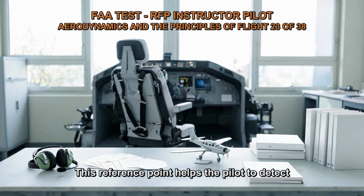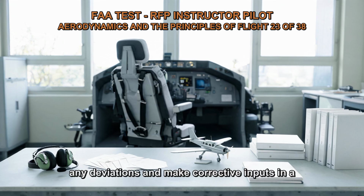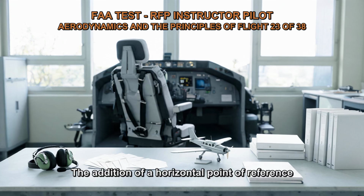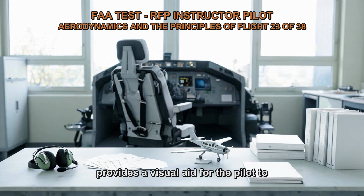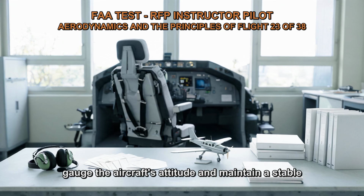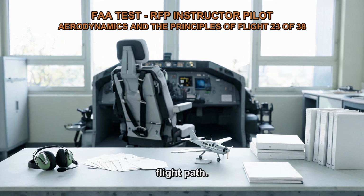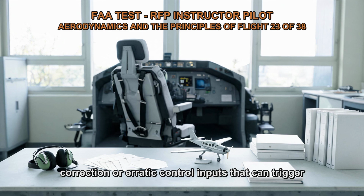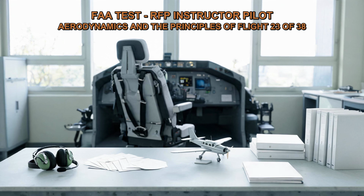This reference point helps the pilot to detect any deviations and make corrective inputs in a more precise and controlled manner. The addition of a horizontal point of reference provides a visual aid for the pilot to gauge the aircraft's attitude and maintain a stable flight path. It helps to minimize the tendency for overcorrection or erratic control inputs that can trigger or exacerbate PIO.